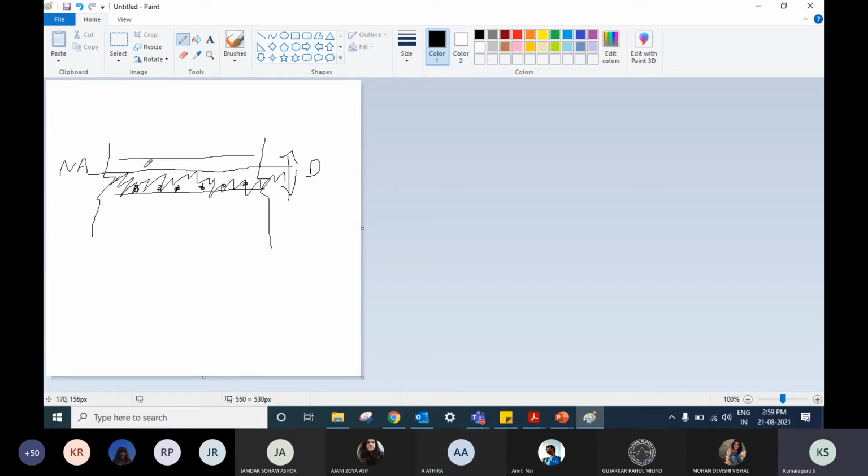That's good. So what happens is we need this effective structural depth. If there is very little depth, you have a very thin slab in design, so you might have to put in many rebars. When you have an increased structural depth, the forces at the outermost edges reduce for the same load that is coming. There's the same fixed load coming from the top, and with a deeper cross section, your bending stresses are reduced. So we need to maintain this depth of the section.